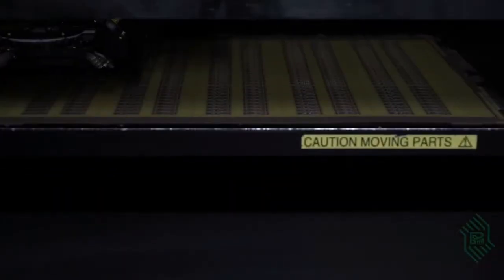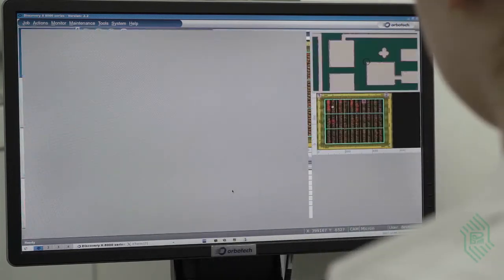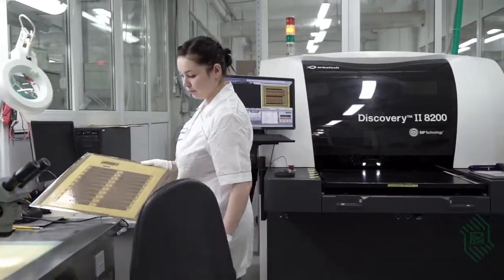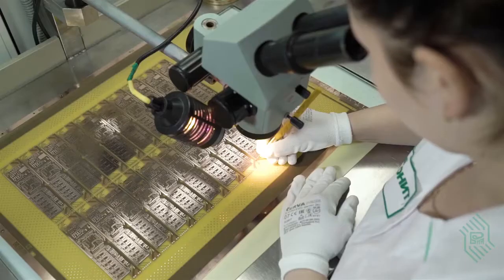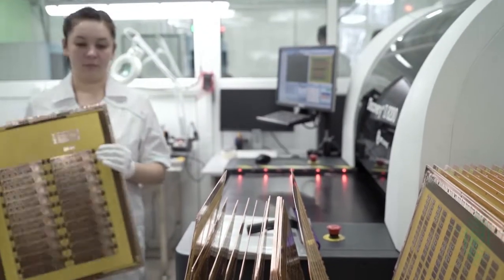The outer layer's automatic optical inspection system scans the panel, receiving a digital image of the etched pattern, and compares it with the reference pattern formed during the PCB's preparation for production. In this case, not only is the quality of the etching controlled, but also the diameters and the hole positioning tolerances. The tested panels are transferred to the solder mask application area.